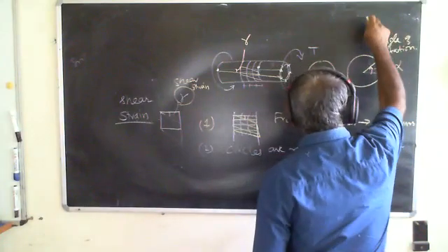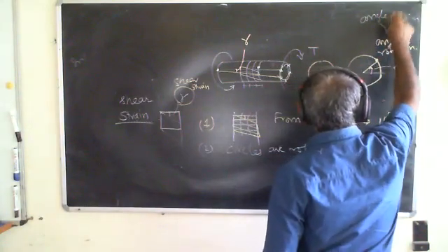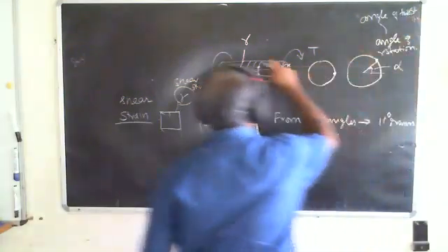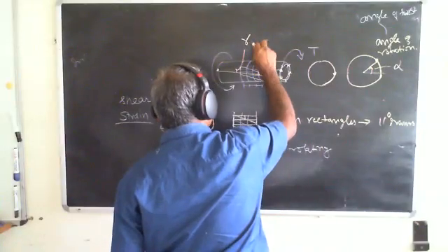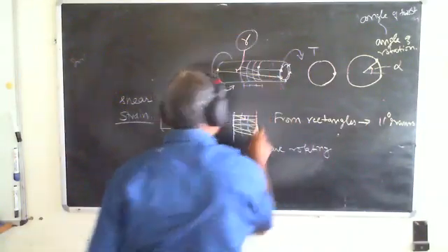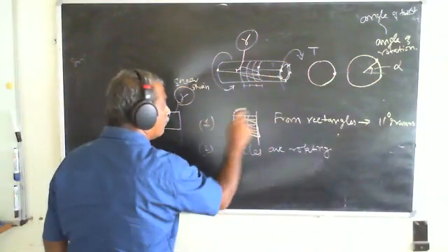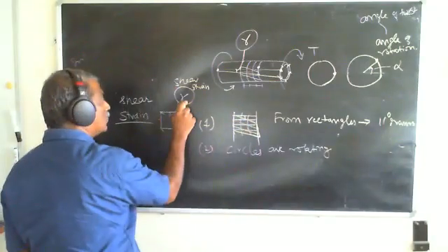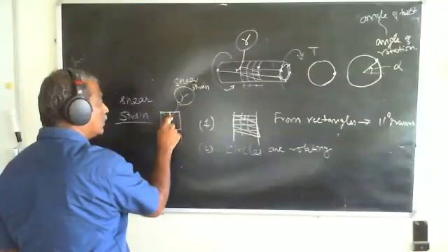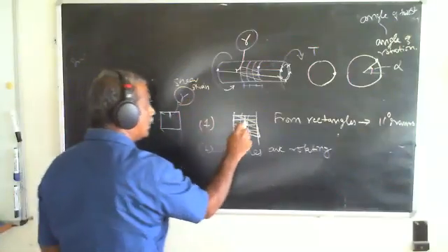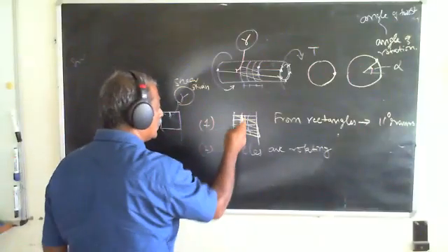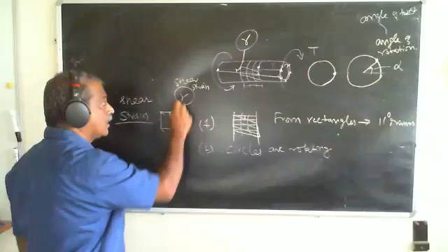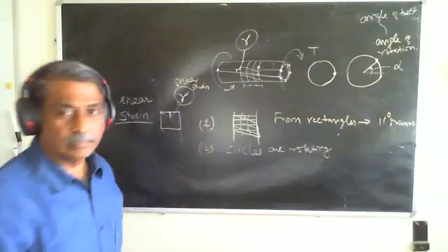This I'll also call the angle of twist, compared to what I call this. This is gamma, because I'm able to identify from the grid that the slant that has occurred has to do with the shearing that happens, and therefore this is a shear strain, that gamma, that I find out.